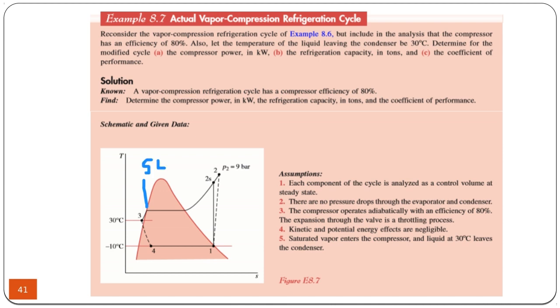So there is more cooling in the condenser than expected. What would happen, let's say, if it was a saturated liquid and at the expansion valve it would come to this point? Then you can see that the cooling effect in this case would be lower than the cooling effect in the second case. Now we will see it with the figures.